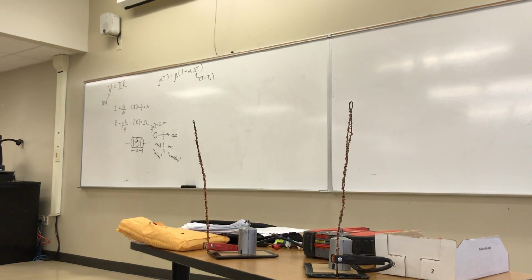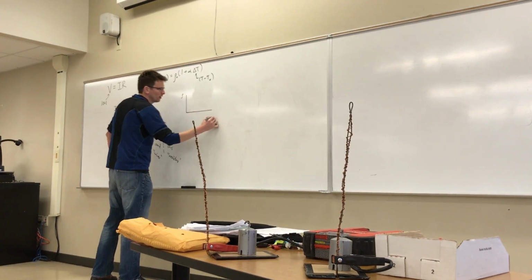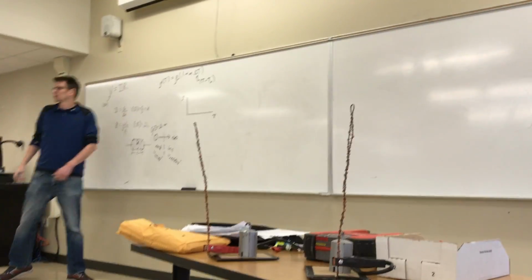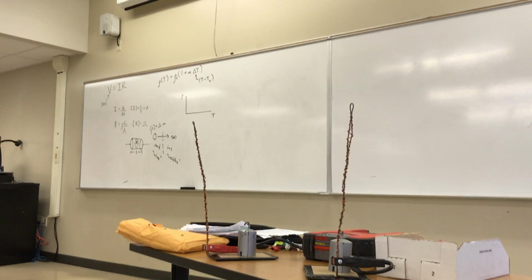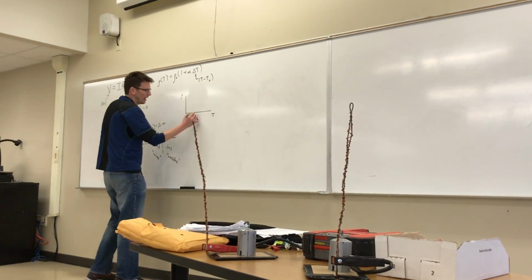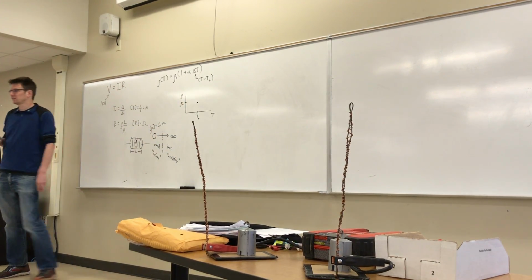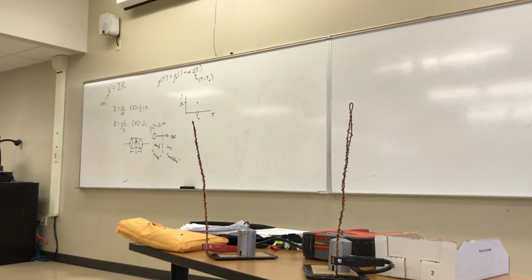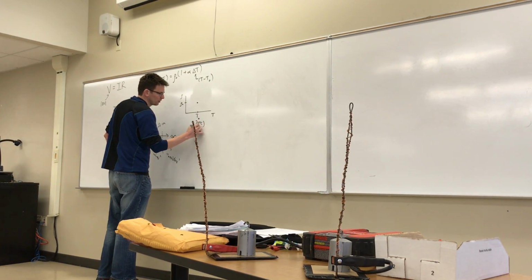So, first of all, if you were to plot the resistivity versus temperature, first of all, there's a baseline. The baseline is that at a certain T naught, you start off with a known resistivity, rho naught. Okay? So oftentimes T naught is said to be room temp, 20 degrees Celsius.